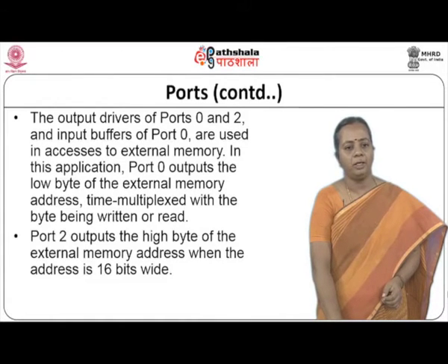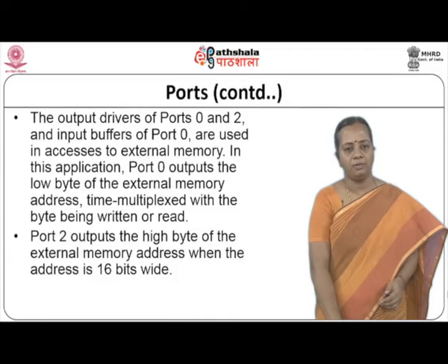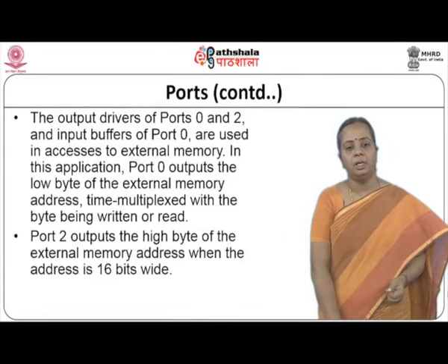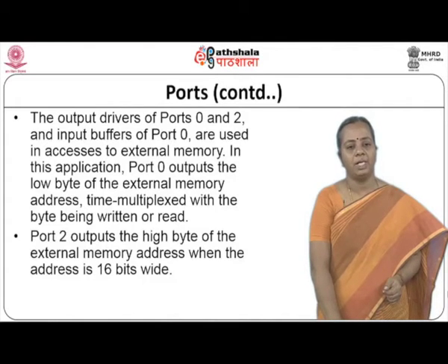Port 2 carries the higher byte of the external memory address. So, if I want to access a 16-bit address of a memory, then port 0 and port 2 are combined together and the address is sent.